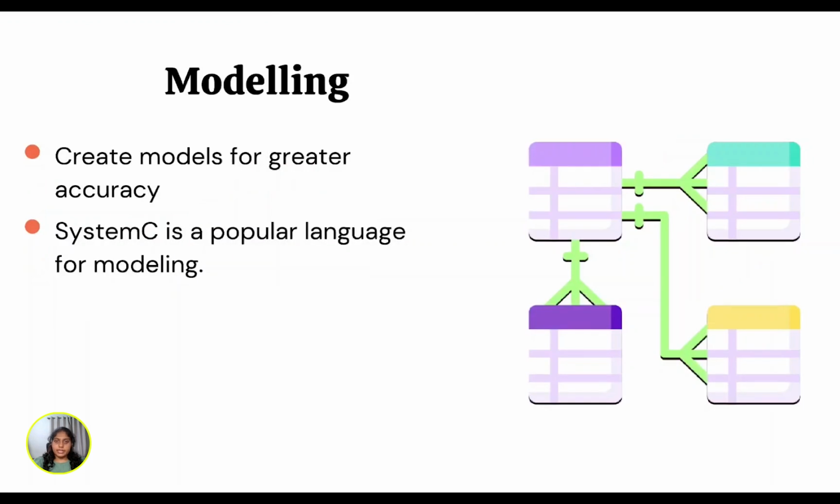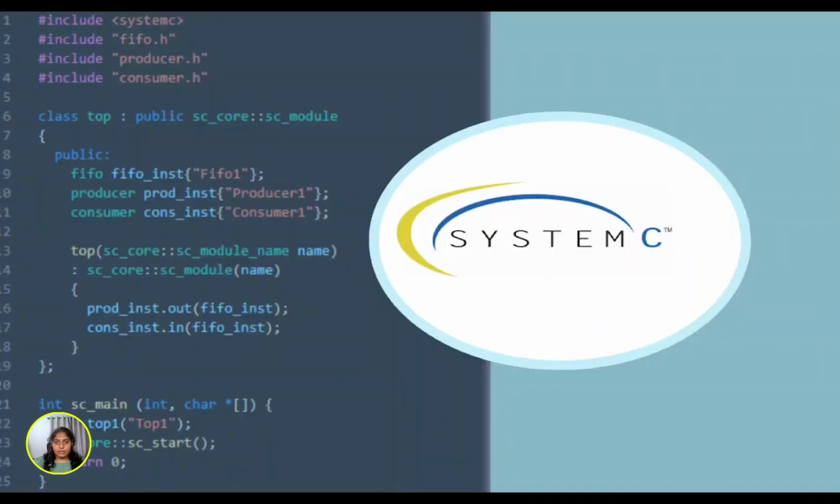Here, more detailed and accurate models are developed to determine if the interconnections and the integration of selected IPs and the communication protocol bus architecture proposed are all in sync to achieve the functionality expected. System architects use high-level languages like SystemC to develop these design models.